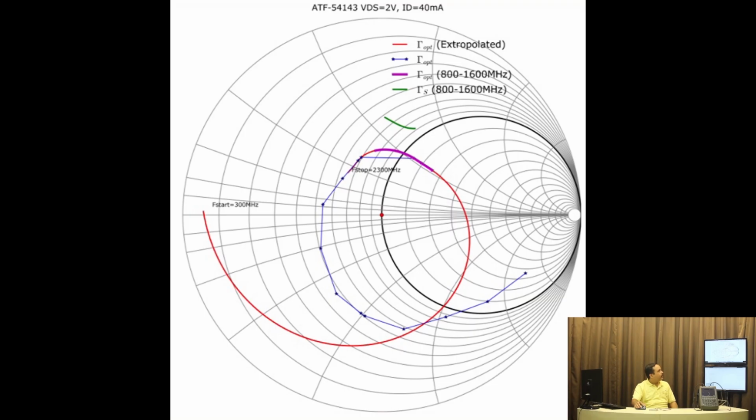So I have implemented my own matching network, and then what I have done is simulated the source reflection coefficient. That is how the 50 ohm source got transformed after introducing some sort of L and C combinations at the input of the transistor. So now you could see it's exactly the same Smith chart as before.